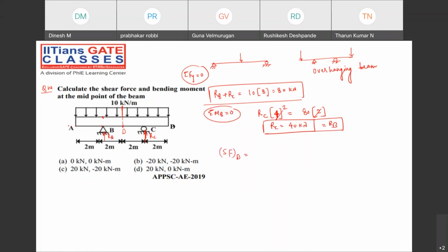Directly calculate. Because of this loading condition, see, I can draw over here. First of all, because of this loading condition and this reaction, you calculate from the left hand side. I said that shear force is the summation of forces either on the left side or on the right side. Do not consider both sides at a time, right? Forget the loading condition on the right side. Whenever the left side forces are there, you know the sign convention.